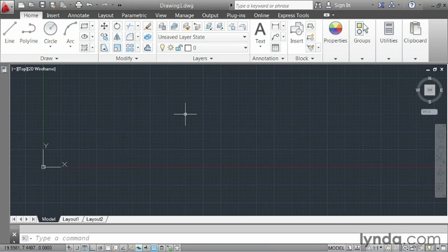At this point, you may be wondering if it's possible to create geometry using coordinates. The answer is yes, you can, although we don't do it very often. Let's try it. Since we're going to be drafting using coordinates, I'm going to make one quick change. I'm going to come down and turn off the dynamic input. Dynamic input tends to take some liberties with our coordinates, and I don't want to get into that right now, so we'll toggle that off momentarily.